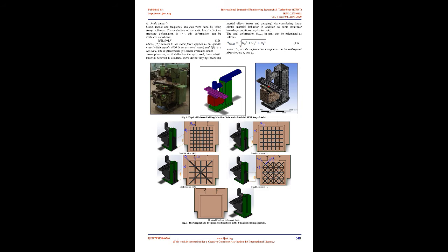Scroll event is triggered continuously whenever the scroll box is being moved. Clicking an end arrow increments the scroll box a small amount, clicking the bar area increments the scroll box a large amount, and dragging the scroll box, the thumb, provides continuous motion. Using the properties of scroll bars, the designer can completely specify how one works. The scroll box position is the only output information from a scroll bar. Another code is written to calculate the vertical and end milling processes as shown in Fig 3. The user will input in scroll boxes the cutting parameters and workpiece material. The outcomes of the code will appear in scroll boxes.